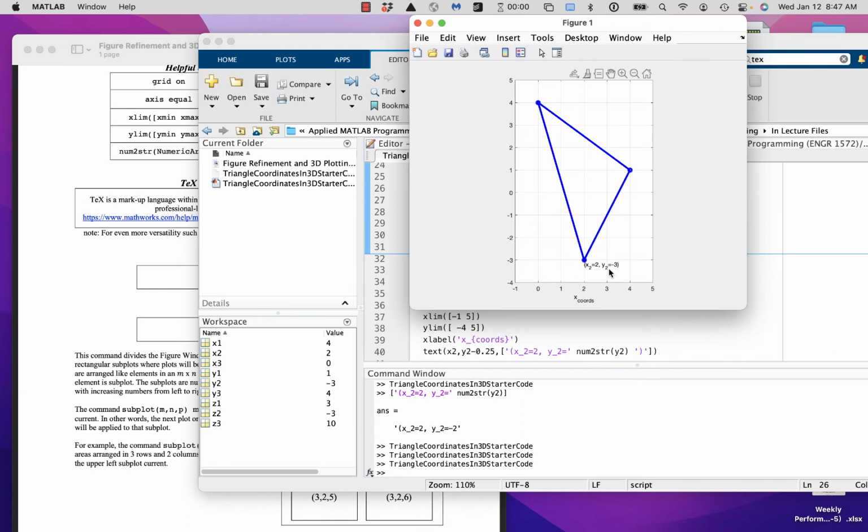I use it all the time to create dynamic character strings, and you can use it anywhere that you have an input or an output that's a string. Examples of functions that we've used so far that can have a string input and that you can use this type of variable with are disp, legend, xlabel, ylabel, and text. Anything you use a string for, you can always make that a variable string using this command.